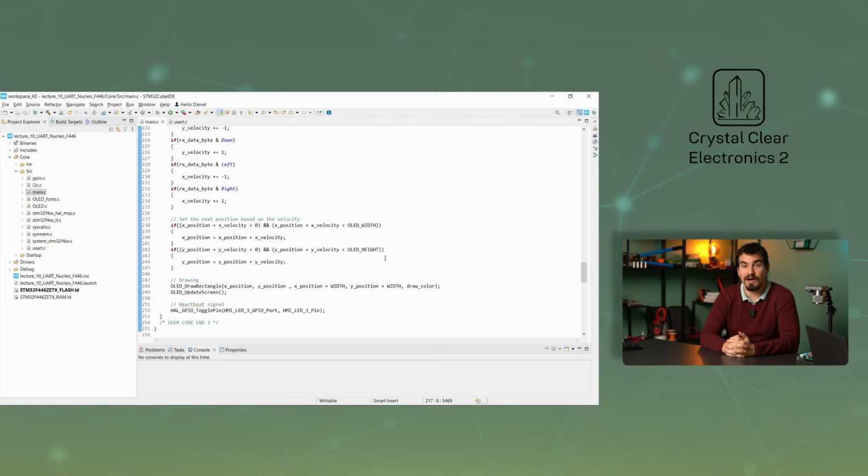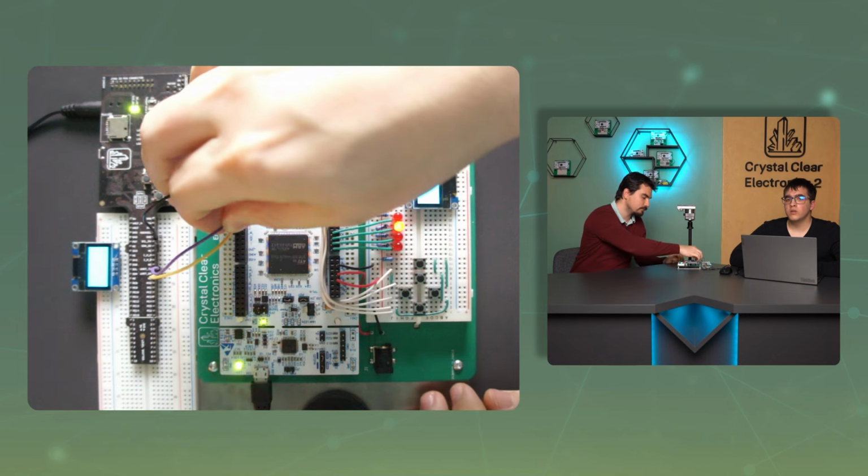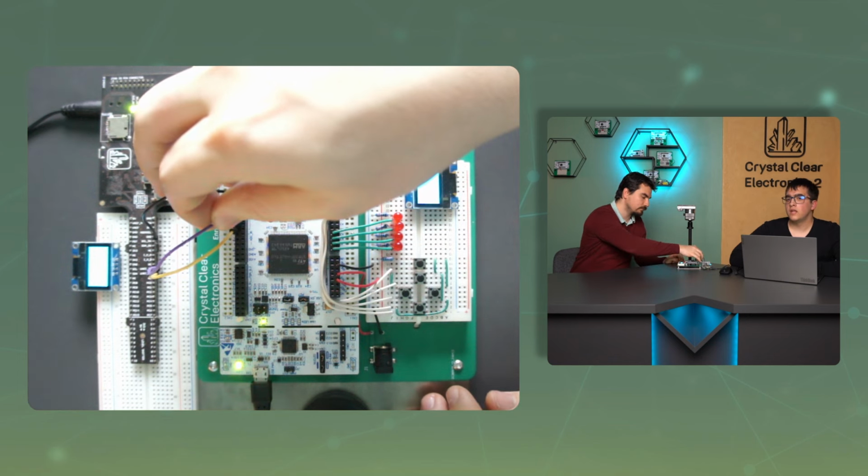If I see it correctly, LED 3 is flashing. Can you tell me what it means? Of course. Each run cycle is indicated by a status change of LED 3. This is called the heartbeat signal and is used in cases where we need to be able to detect that the program works correctly. It can be observed that when the communication is broken, the heartbeat rate is slower than if two devices were connected. How does it work? What slows down or speeds up the flashing of the LED?